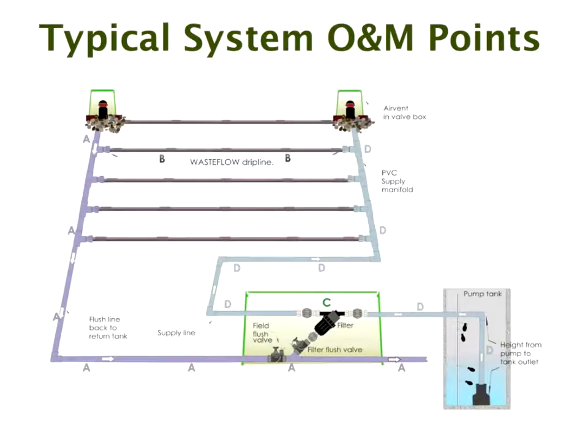Okay, we'll go back to this standard drawing of a zone and talk about where we have to worry about the maintenance. Here we have a pump tank. Inevitably, you're going to get build-up of solid material in the bottom of the pump tank.